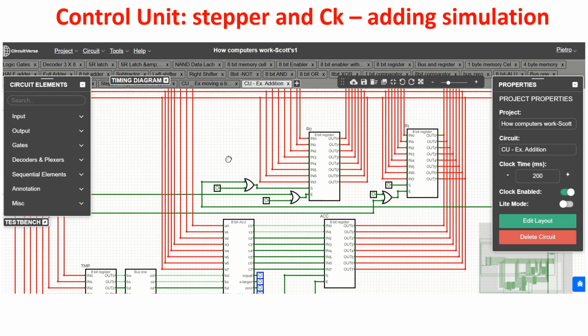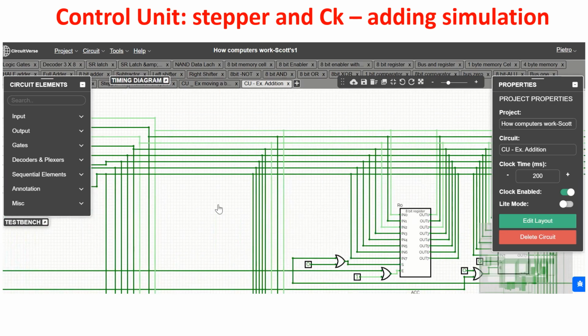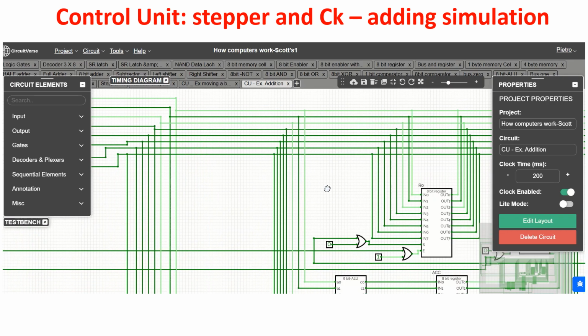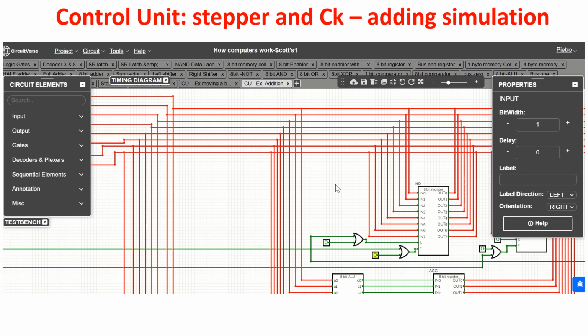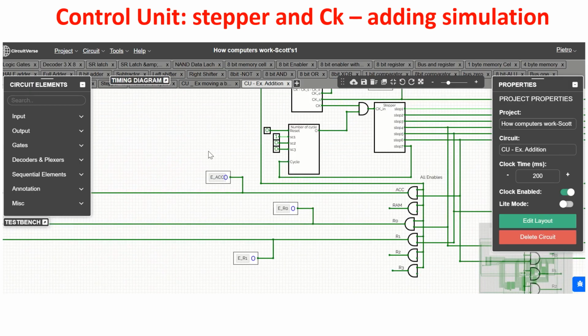So we go to see what there is inside R0, putting the content of R0 on the bus, giving an enable pulse, and we see there is the number 5, because this is the first bit, the second bit is 0, and the third is at 1, so this is the number 5. So it worked. We free the bus again, and we can see now the timing simulation.